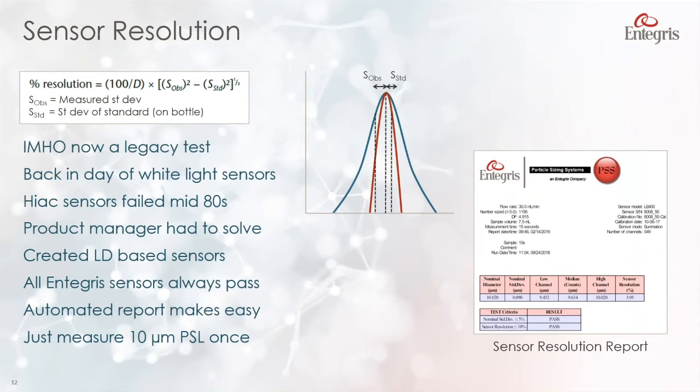The sensor resolution test is basically saying, are you working with a good sensor? So when we look at the standards we use, no standard is perfect. There's a particular spread to the standard itself. So we call that the standard deviation of the standard, which comes from the certificate of analysis on the bottle of the standard you're using.